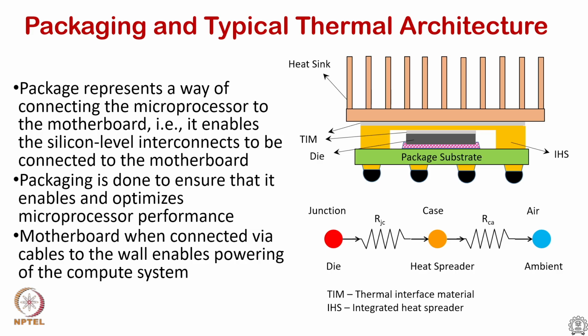So, here is a typical example of what we call packaging. There is much more than the thermal part; there is also the electrical part where the power is being delivered and so on. So, for the sake of discussion for this course, this is the die, which is affixed to a package substrate. There is this layer, which is the underfill layer, and that is affixed to the package substrate.